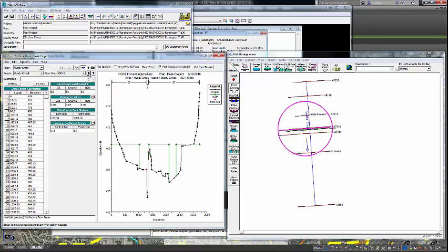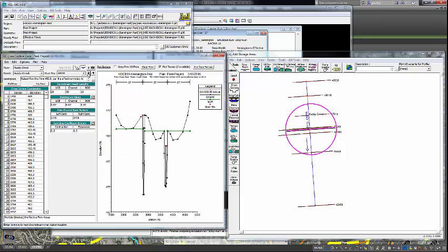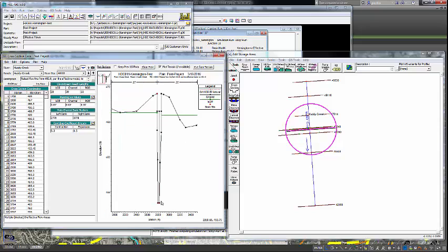So I'm going to walk down the stream. These green lines, don't worry about them. That deals with ineffective flow, and it's a whole other set of calculations, but I had to put that in to make it realistic. Here we're at the bridge, and then there's actually a relief bridge over here. When you've got that much water flowing through this one spot, let me zoom in, sometimes you need an area where it can spill over and continue to flow without overtopping the road.